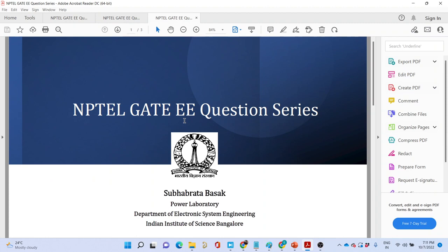Sir, how did you know zeros contribute to the lag? If there is a zero, what is the angle contributed by the zero? Say s plus 2. What is the angle contributed by the zero? Tan inverse omega by 2. There is plus tan inverse of omega by 2. Lead, not lag. Getting my point or not?